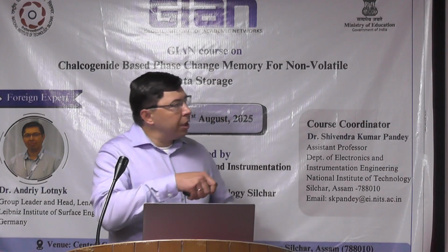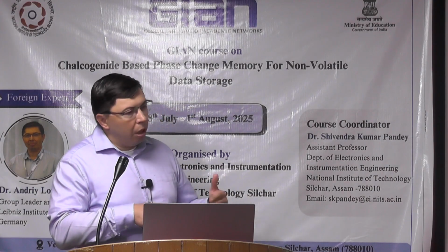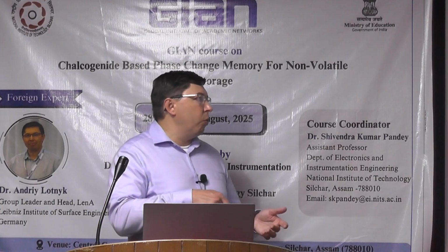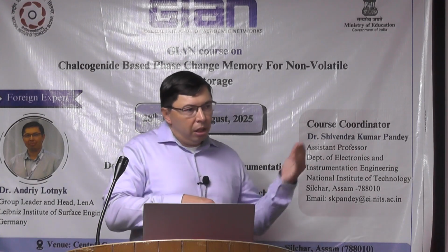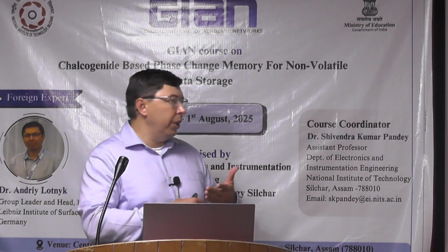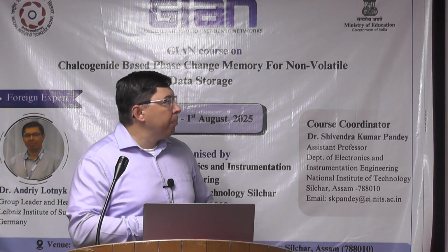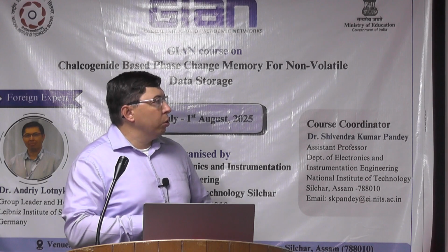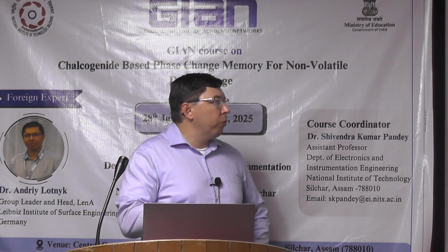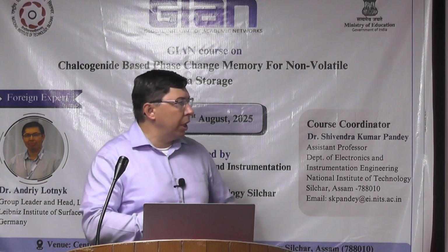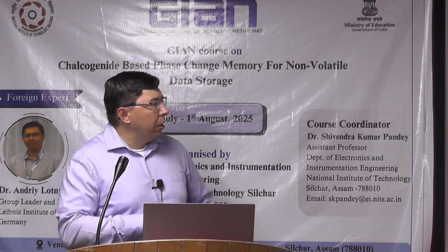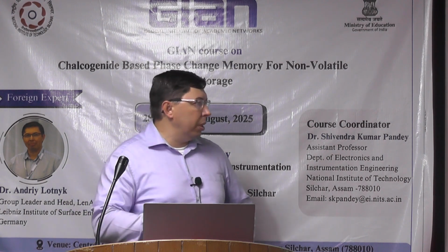This is because the crystallization of amorphous materials starts from this native oxide layer, so you have an additional interface, and so you influence your crystallization kinetics. In this case, data retention in amorphous states is also reduced by the presence of the oxide layer, since this oxide promotes crystallization.